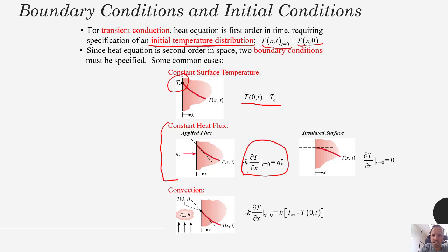This is essentially a surface energy balance on that left side, and we're just saying that this constant heat flux that's coming in is going to be the same as the heat leaving that control surface by conduction. So we're just saying the heat coming in is just a constant. It doesn't even really matter how it's getting in. We just know that it's a fixed mathematical constant.